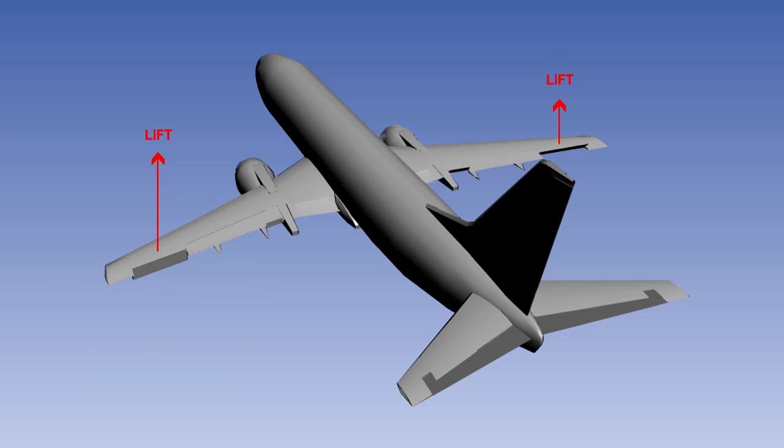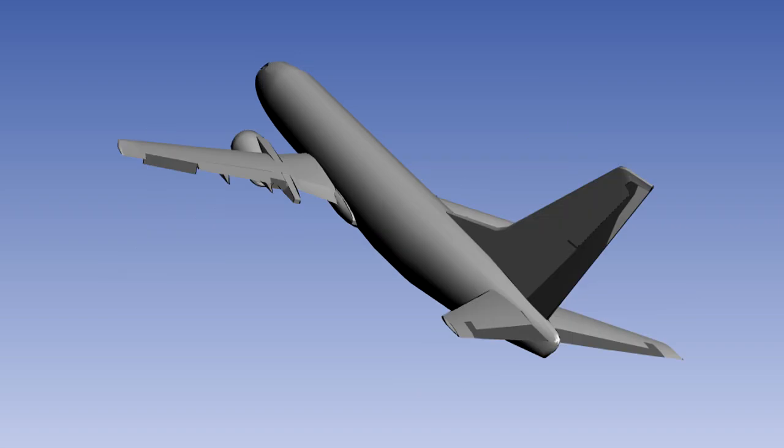The ailerons are flap-type controls, but their angular movements are in opposition to each other. When one aileron is angled up, the other is angled down. Consider the aircraft in the graphic. The left wing has the downgoing aileron. This will increase the camber and increase lift. The upgoing aileron on the right wing has a reduced camber, so its lift will be reduced. The lift forces are now out of balance, and the aircraft will roll to the right. It will continue rolling to the right until the ailerons are returned to the neutral position by the pilot.